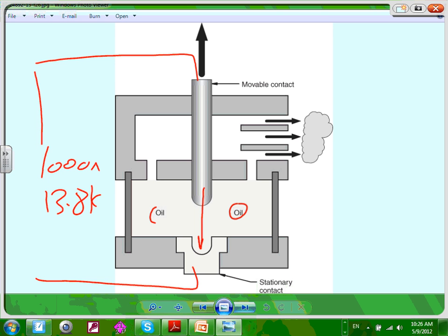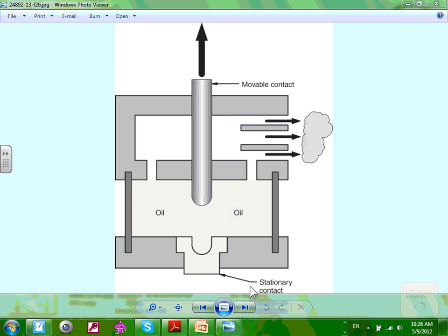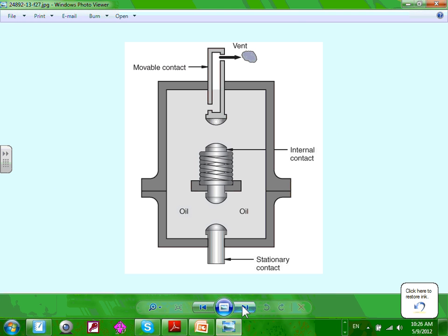These are high voltage, guys, all of them. Now, remember that whole venting issue you're going to create? When you interrupt, you're going to create heat and so on. All this will be vented out. Otherwise, if you increase the pressure inside this tank, what's going to happen to this tank? Explode. So that's why they call it vented. Because after the explosion inside it to interrupt the arc, it vents the energy out.